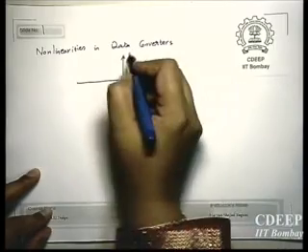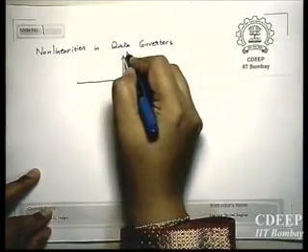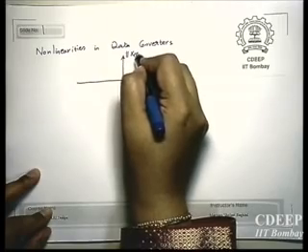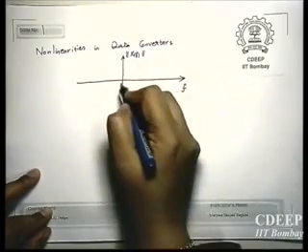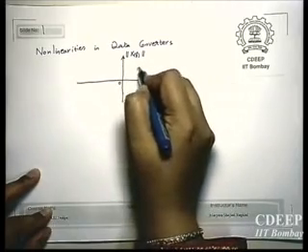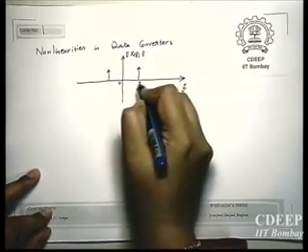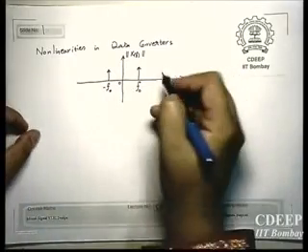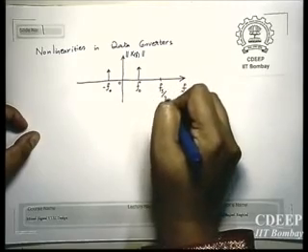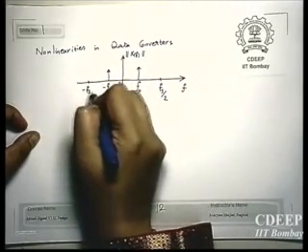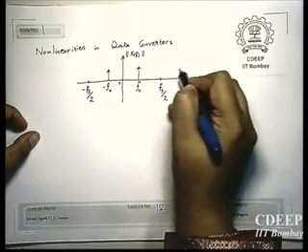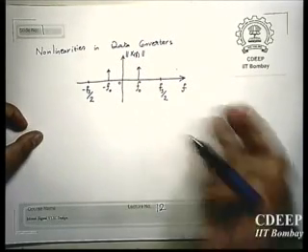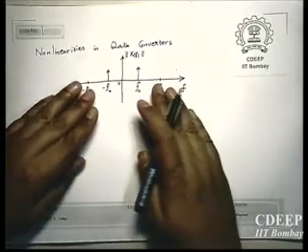This is F, and this is the magnitude of signal X of F. You have two main components at F0 and minus F0, and then you will have the sampling frequency, and ideally the spectrum will be repeated, of course with a reduction in amplitude.